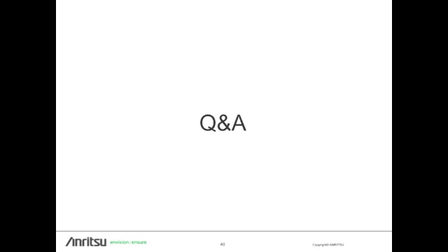All right, great. Thank you. So next question coming in. What is the best way to determine power in transmitters, such as an FM broadcaster? There's one of those non-trivial questions again, because it says best. Well, the most accurate way is with a power meter directly connected to the output, calibrated with a calibrated attenuator, for example. A lot more convenient if there's a test port with a known coupling factor. You can measure the power, again, with a power meter and then offset the reading.